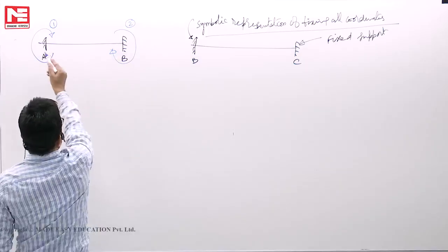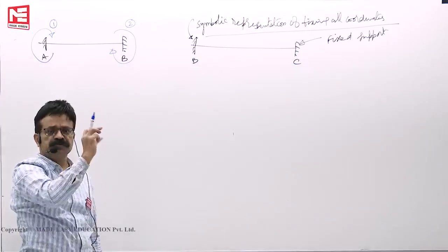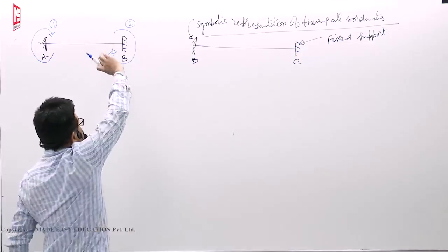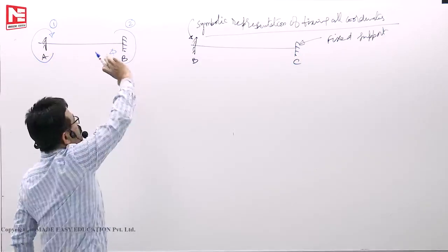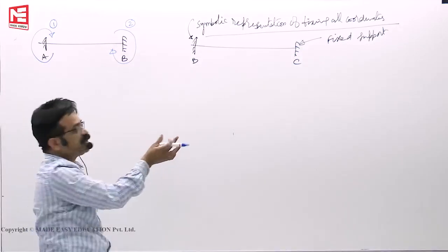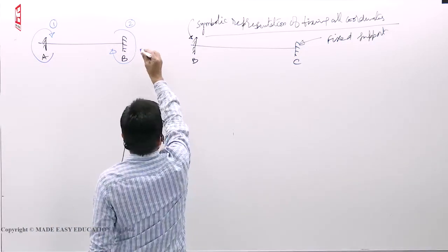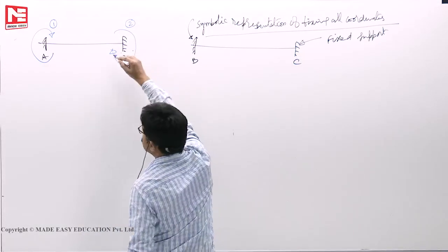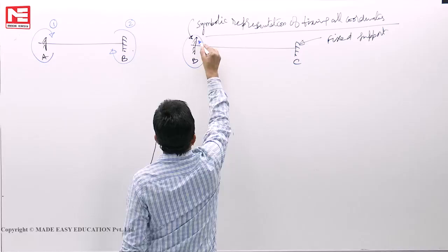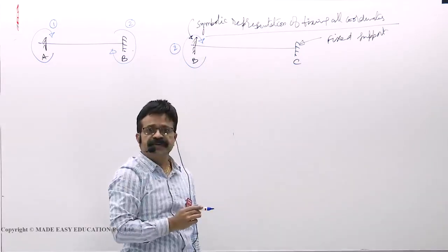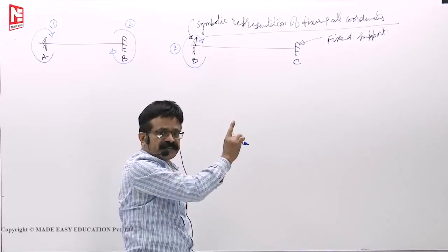If at B, for the member BA, coordinate 2, these coordinates 1 and 2 are given to the displacements. If theta BA is clockwise, say, theta BC has no choice, it has to be clockwise only. That's why, since coordinate numbers are given to the displacements, here also the same direction should be there. You should not give any coordinate number at C because it's a fixed support.